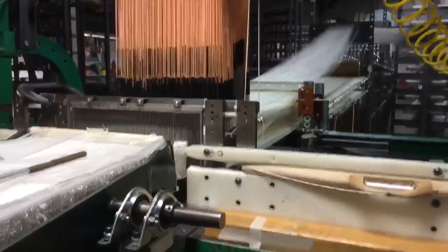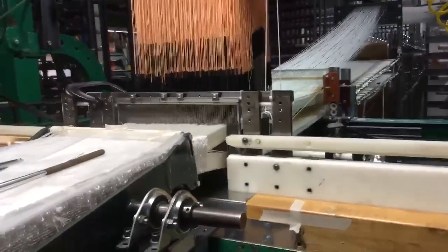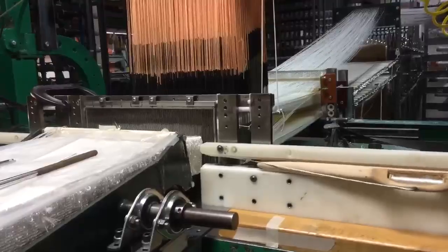And I have one more video I'll show that may be of interest. This is an arc jet test. You're seeing close to a side view of the arc jet article I showed earlier. So this is 4 inches in diameter and a little bit of an oblique side view. And this is 660 watts per square centimeter, so it's extremely hot, very high heat flux in there. And what you'll start to see in a minute is that there's actually a little bit of melt flow. You can start to see these little waves developing on the edges of the coupon where there's some shear forces.